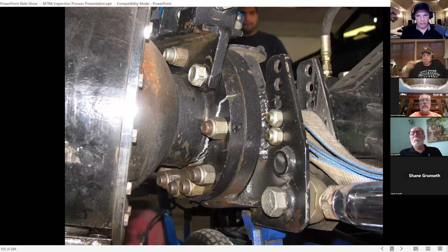So when you're doing your tech inspection, when you're looking at these wheel restraint systems, be sure to inspect the hardware. Look for cracks. Sometimes the drivers aren't aware that they have damage. So it's one of those things where you just have to poke around when you're in there with your flashlight, checking everything. Make sure that you don't see any cracks anywhere that are just going to fail in the middle of a show. You'd rather catch it beforehand.